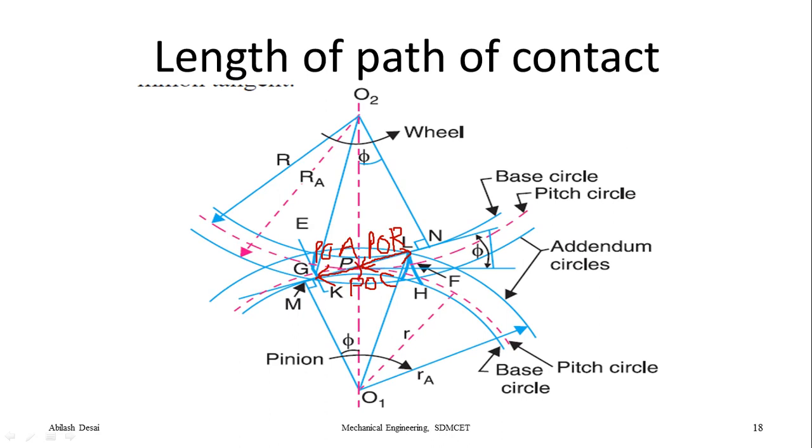We first used this triangle to solve for the path of approach, so there we got everything with respect to capital R. For the path of recess we took the lower pinion part, and from this triangle we got the small r values. So it is only with respect to the radius that we need to understand this now: the RA, and here this RA and this R.